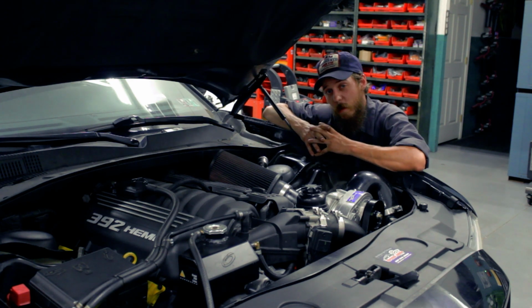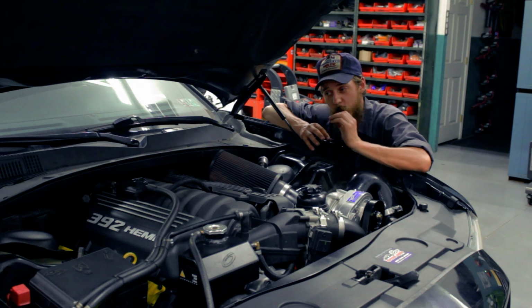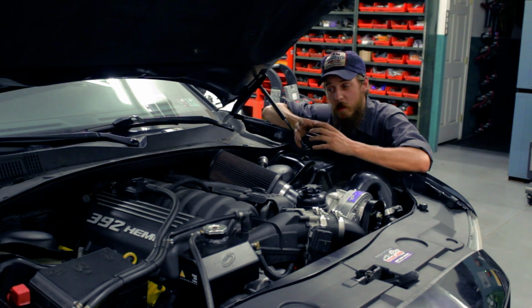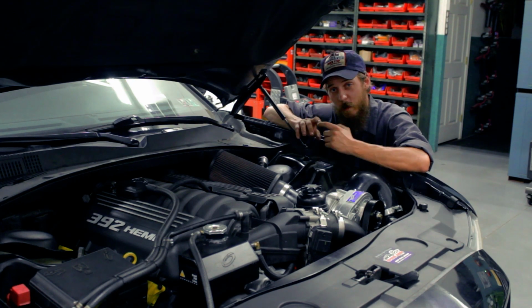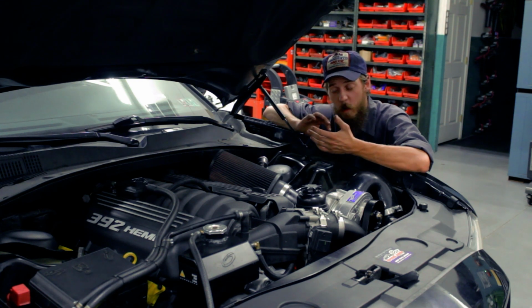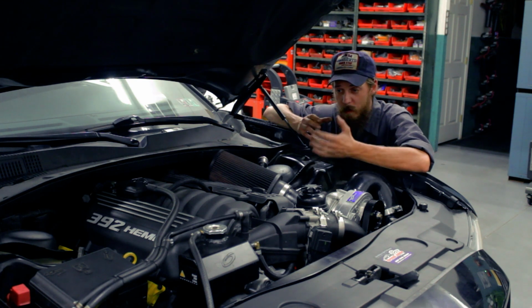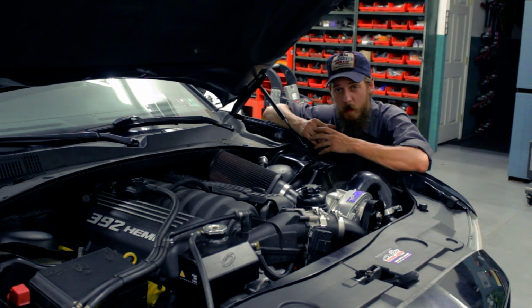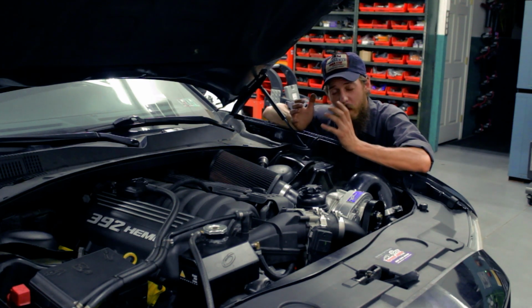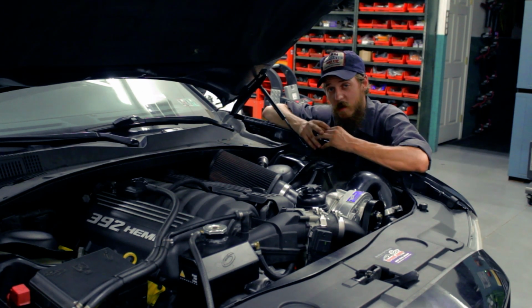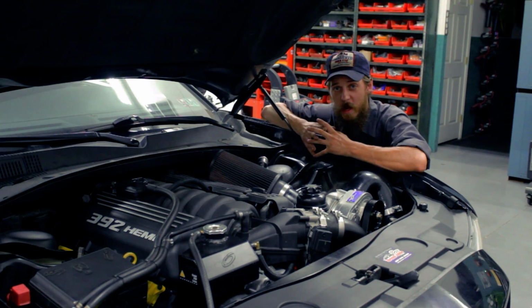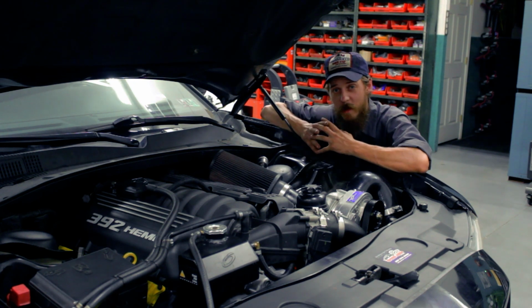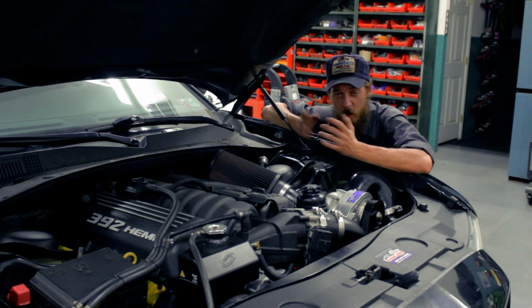Instead of getting stuck in our mind that there is a specific fault and we're trying to prove that fault, what we need to do is allow the data we collect and the information we can gather based off of service info, schematics, and what we physically read with a meter, a scan tool, a scope, temperature sensors, infrared thermometers, whatever it may be, to guide our decision-making process instead of our own preconceived notions, our hit databases, our fixed databases, what the guy 3 houses down said he's run into on every Dodge Charger ever.